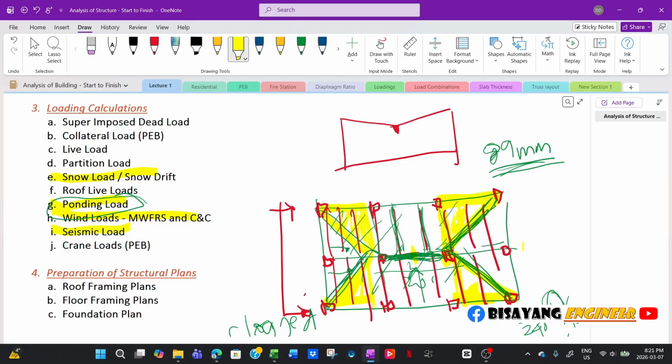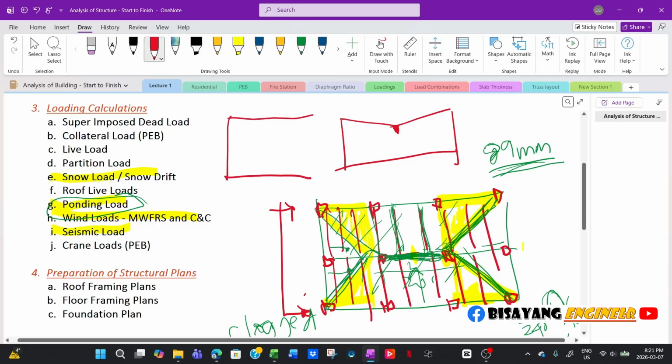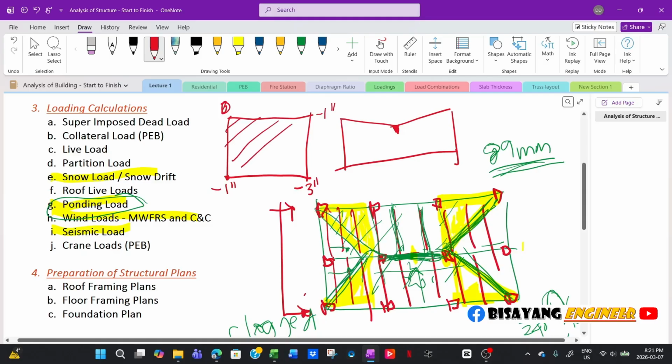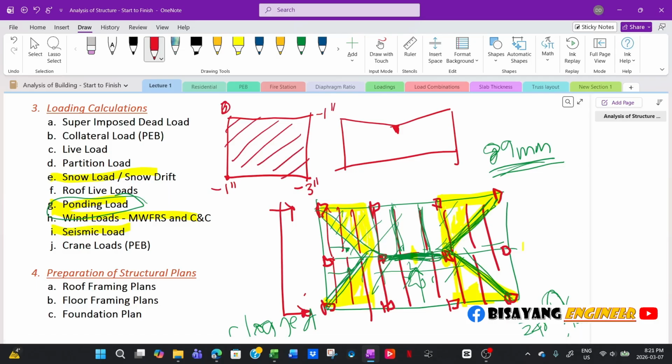is it in surveying where if you have, for example, four sides, and this elevation is 0, and then they say this is minus 1 inch, this is minus 3 inches, and minus 1 inch as well? All you have to do to determine the volume is get the area and then the average height. So your average height is 0 plus the absolute values 1 plus 3, and then divide by 4, and that's your average height.